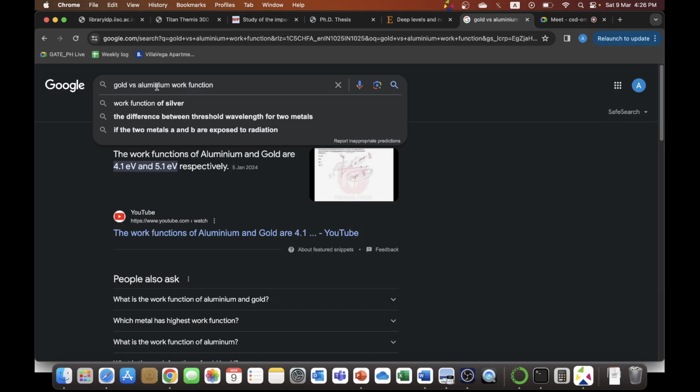This term I'm not even worried about. All right, and phi ms for B will be 4.1 minus 4.9, which is minus 0.8 eV. This entity, whatever it is, it will be a constant. So you can see that the VTH for A will be this entity plus 0.2. Let's say this quantity is 0.8 eV, 0.8 volts. Okay, so what will the VTH for A be? VTH for A will be 0.2 plus 0.8, which is 1 volt. VTH for B will be minus 0.8 plus 0.8 equal to 0 volts. So you can say VTH A is higher than VTH B, right? This is the correct option.